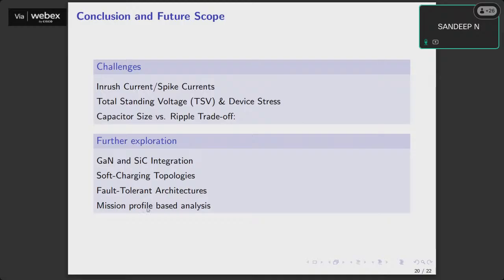So in this case, what is going to happen? Even though we say that our inverter is designed for a PV system, rarely will an analysis be done by considering the actual PV generation data, right? So we take a PV, then what max do we do? We change the irradiation from 500 watts per meter square to 1000, or we change the temperature from 25 to 40 degrees. Those are all step changes, right? So that is what we test.